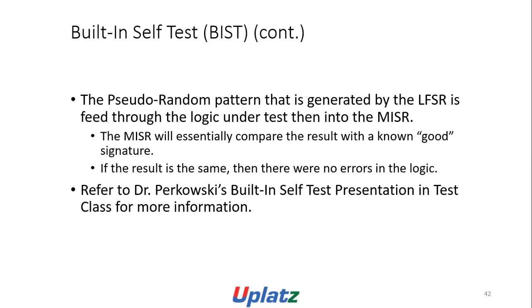Built-in self-test, continued. The pseudo-random pattern generated by the LFSR is fed through the logic under test and then into the MISR. The MISR essentially compares the result with the known good signature. If the result is the same, then there were no errors in the logic. Refer to Dr. Perkowski's built-in self-test presentation.